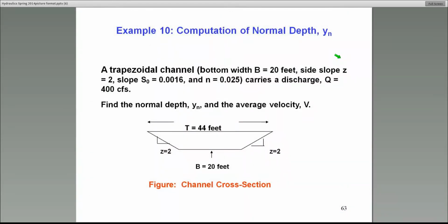So in this case, I have a trapezoidal channel. They'll give you a trapezoidal channel, the bottom width, side slope, Z of 2. By the way, the side slope in some references might be referred to as small s. Be careful. But it's basically Z horizontal, 1 vertical. That's what it means. And that's what I've shown you right here. Z is 2 to 1. Okay. So for every 2 feet across, 1 foot vertical. So that's Z. In this case, is 2.